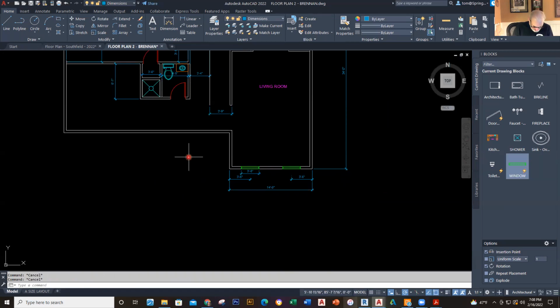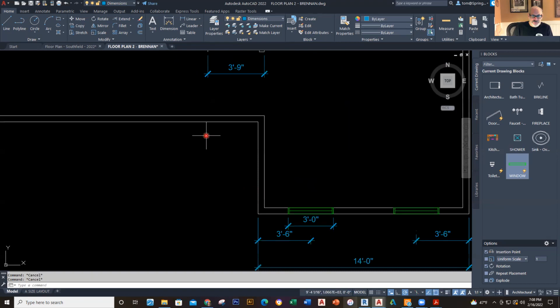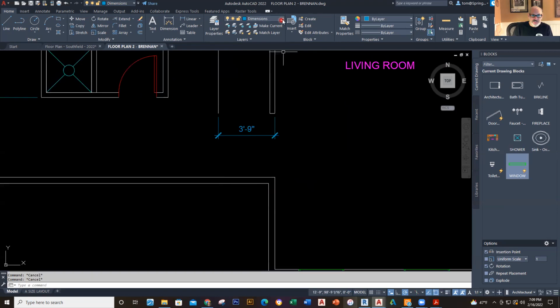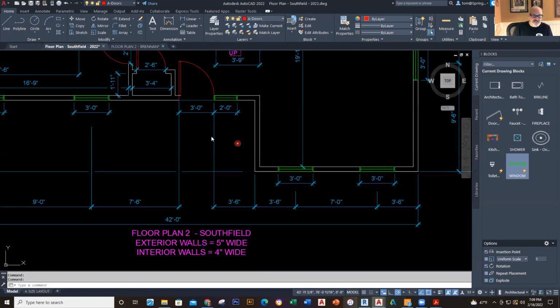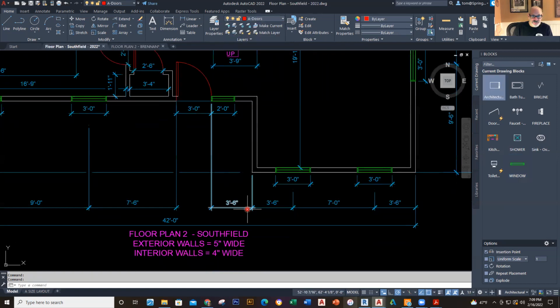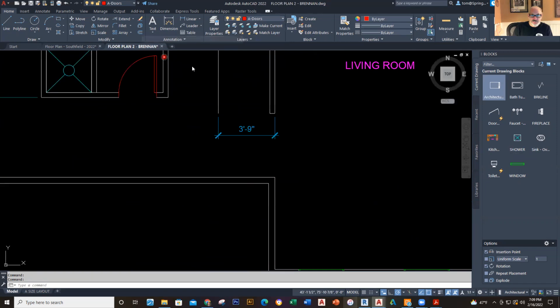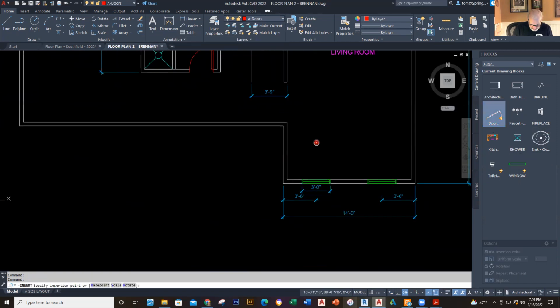Now over here, there's a front door. I'm going to place the front door right here. So let me make sure I've got the dimensions for the front door correctly here. Correct. And the front door is actually 3'6" from this wall. So the door is 3'6" from the wall there. So I'm going to place a door. So I'll start my door command here, and I want it to be 3'6" away from the corner there. So I'll touch it here, and I'll slide along here, and the distance over is going to be 3'6".